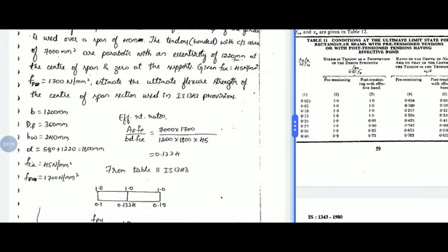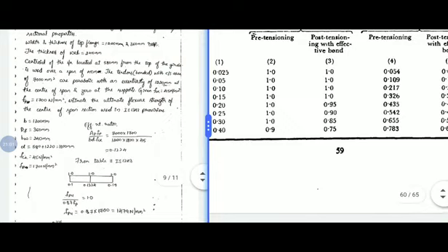For effective depth, you can observe the distance of centroid from top is 580, and eccentricity, meaning centroid to location of tendon, is 1220. So overall the effective depth of the beam is 1800 mm. FCK 45 Newton per mm square and FP 1700 Newton per mm square. First, effective reinforcement ratio AP FP by BD FCK. On simplifying, we will get 0.1224. So it lies between 0.1 and 0.15. For both we have 1.